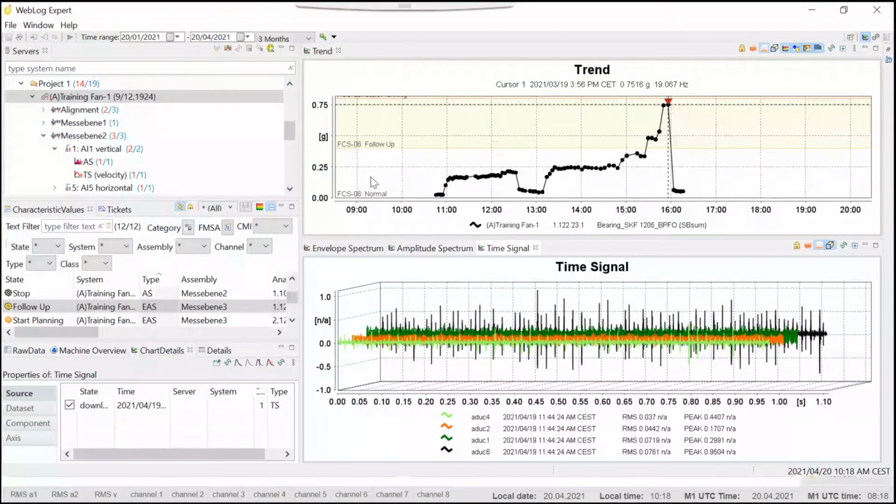If I go back to my earlier example, we have a series of different frequencies set up which relate to specific issues on a machine. They may be unbalance or misalignment, or there may be specific bearing problems or specific gearbox problems. And between those, we will get a number of these trends that come up. And then if any of these go into an alarm or an alert area, then we can go into a more detailed analysis and generate some information about what needs to be done to fix the machine before things go too badly wrong. So that's our more detailed package.